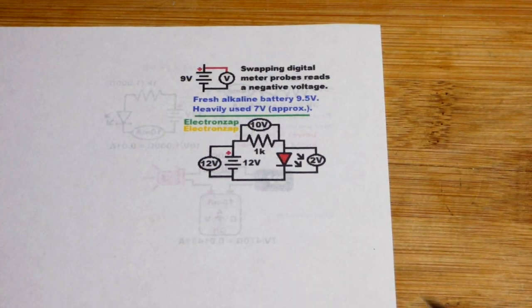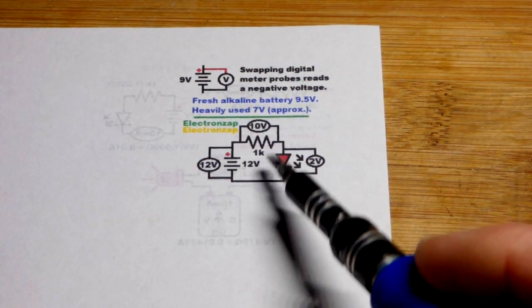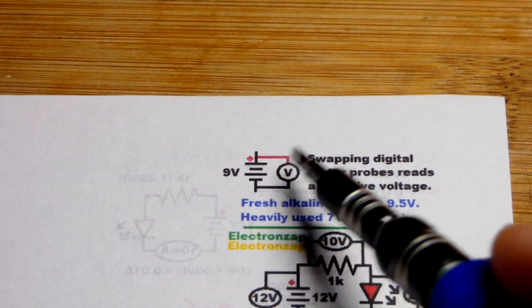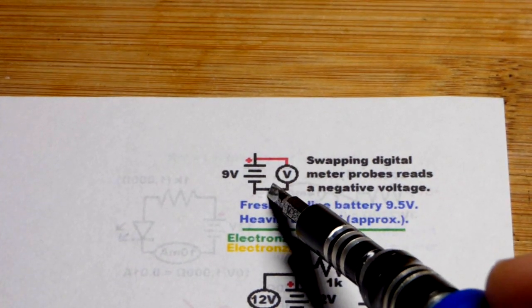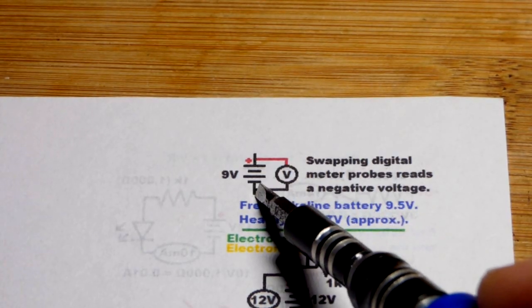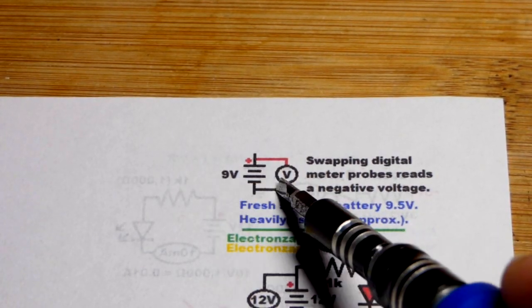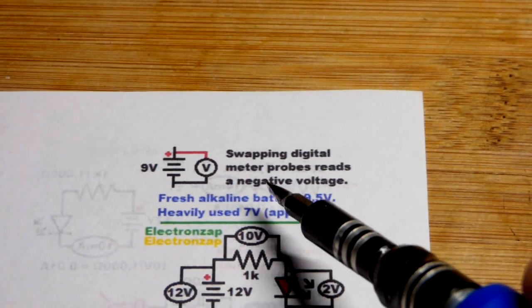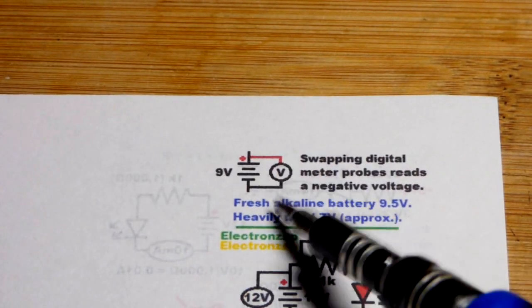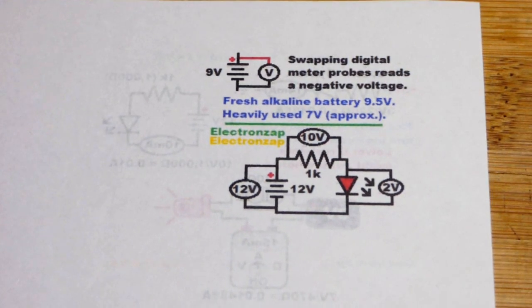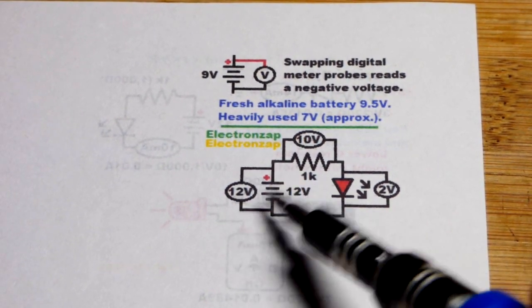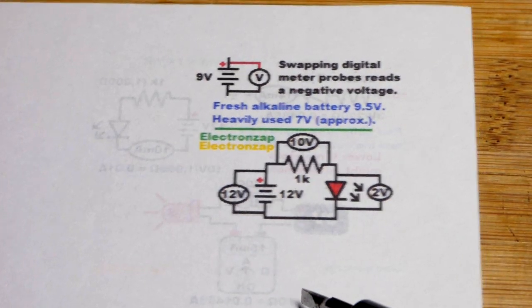So now when it comes to measuring voltages, especially for the first time, it's good to get practice with simple circuits. So you can measure the voltage of a battery. If you have a 9-volt battery, you just put the probes across the battery, set the digital meter to measure voltage, and you should see 9 volts in this case, using a digital multimeter. That's really all people use these days. If you put it backwards, you'll just get a negative voltage. That's all it's telling you is the probes are backwards. Perfectly fine. So yeah, 12-volt battery, again, you should measure that it's like 12 volts.